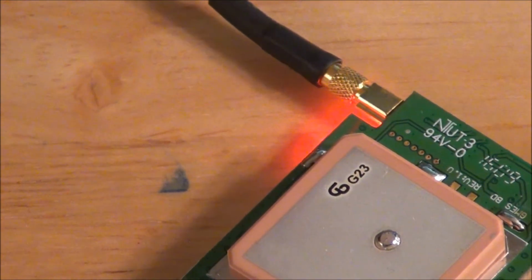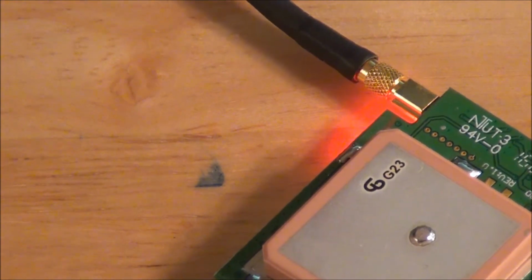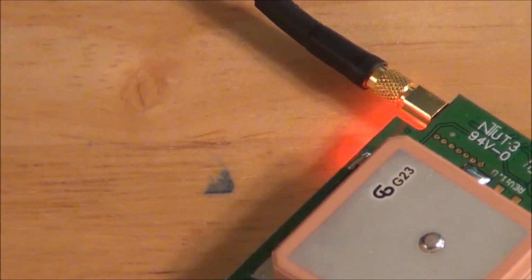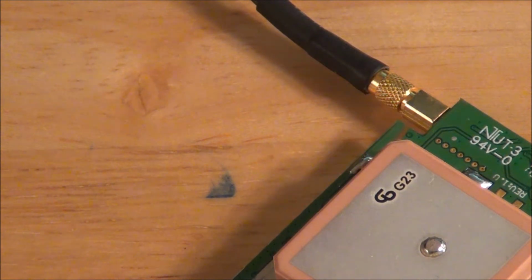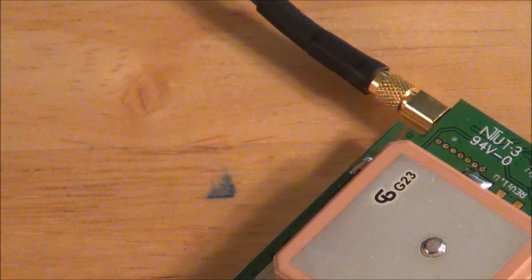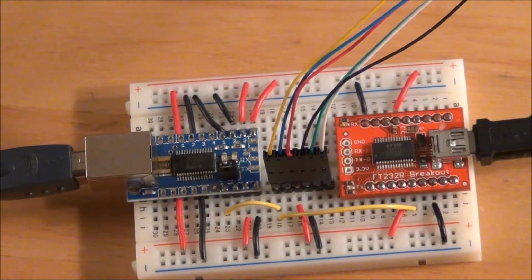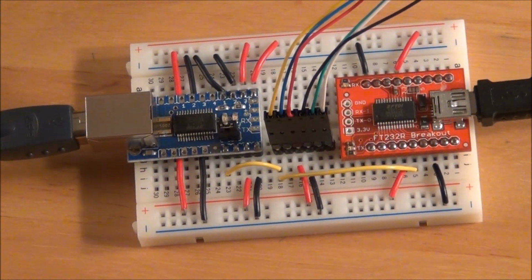With the PMB688, there's a LED that blinks on the back of the board, and that's while the unit is getting its GPS fix. Depending on how long it's been since the unit was turned on last, if it was turned on more recently, it'll take less time. Once the PMB688 has enough satellites tracked that it perceives that it has a legitimate GPS location, then that light will go solid, and then you know you're good to go. So let's go ahead and take a look in the Device Manager in Windows for how these two boards appear.